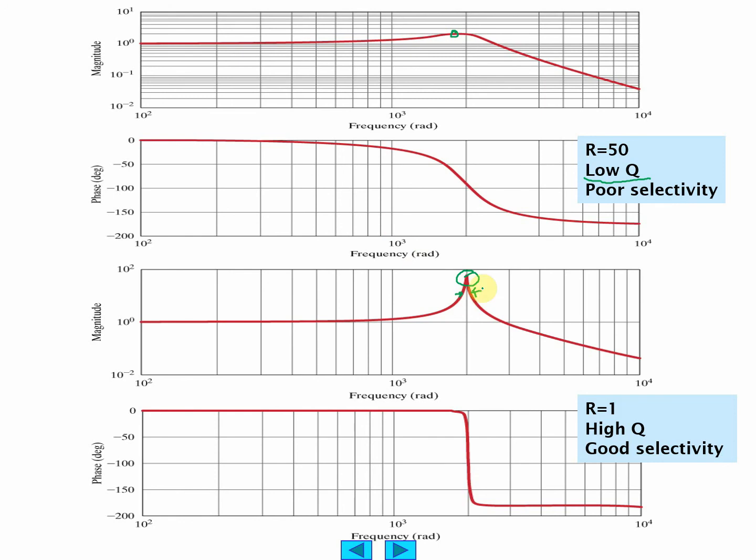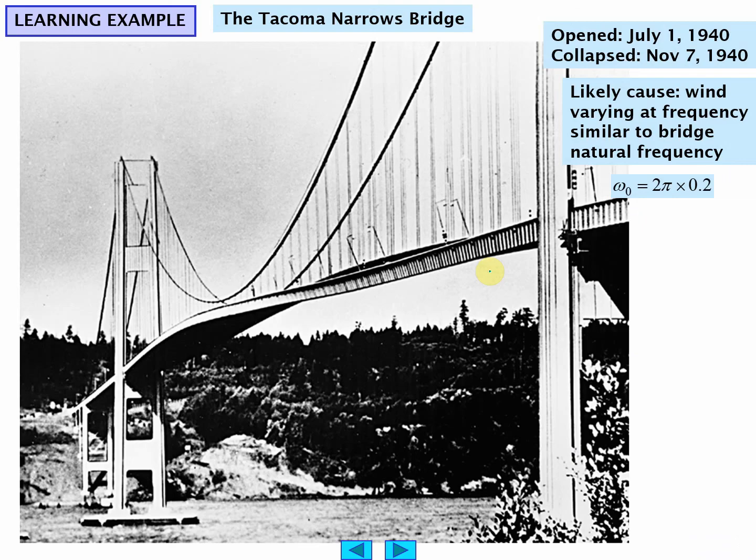Okay, so that's why people want this. They get a very narrow band pass. They can zero in exactly on the frequency you want. And remember that when you're designing things for use in the real world, you want to send a signal down a wire at a particular frequency, and you want to tune for that frequency exactly to reject extraneous noise. You want your information. You don't want everything else, which is why people do these circuits.